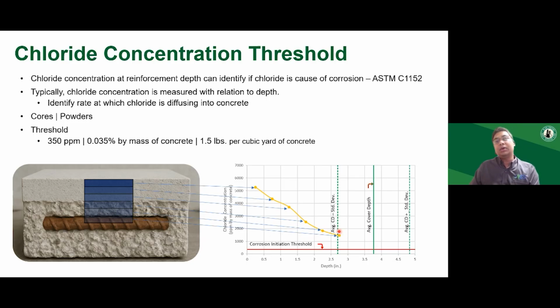If this last data point is below this line, then it's likely that it's going to take a few more years before the corrosion might start. But this corrosion initiation threshold and the rebar cover depth are really critical pieces of information.